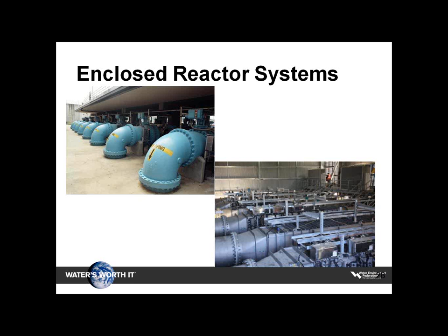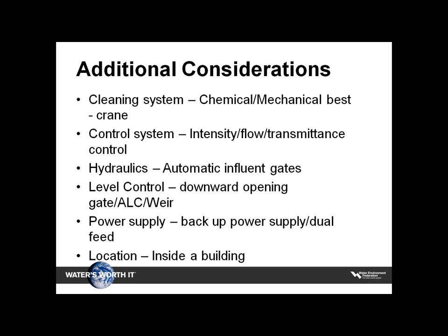And here are pictures of enclosed reactor systems. The top picture is a relatively large system in Georgia where they essentially get basic level disinfection. And then the bottom is a system in Melbourne, Australia, where they're trying to achieve UV disinfection. Enclosed reactor systems, if we have filtration, discharge requirements can be very successful, can be used, very simple to install and easy to maintain.